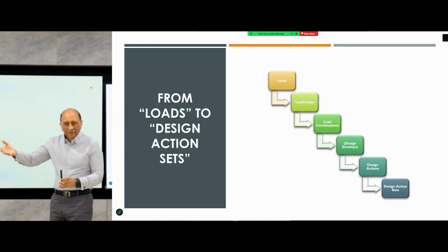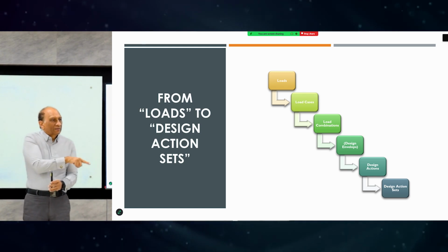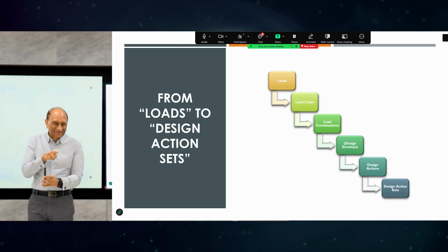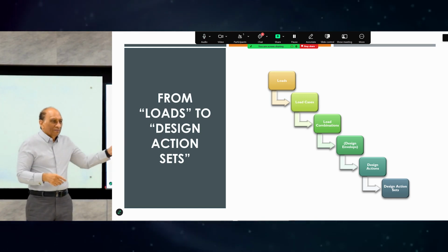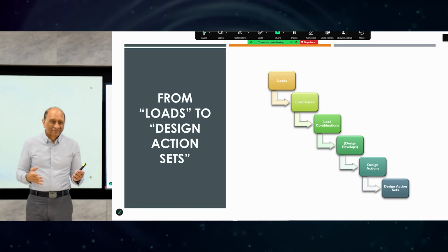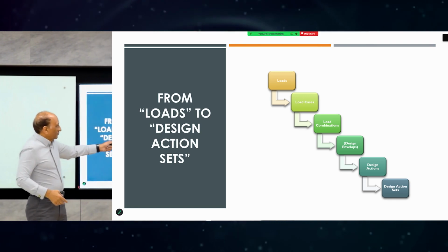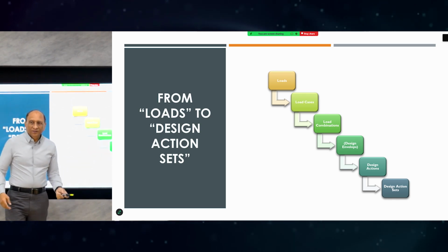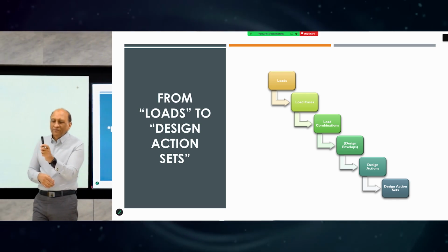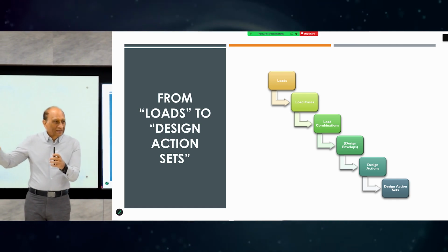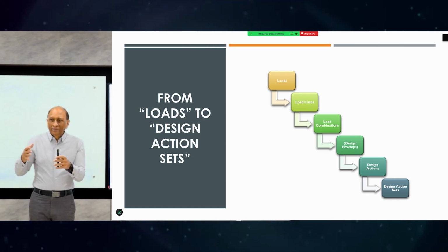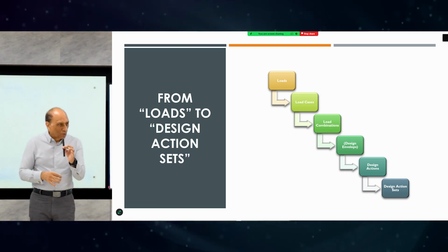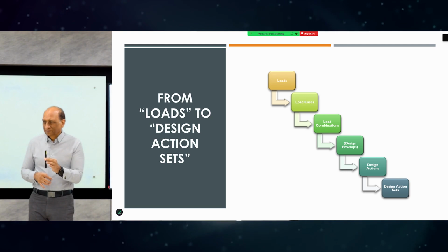So dead load, live load combined in different order, with wind load combined with different order. Remember, wind load combined with 20 different directions. So suddenly, lots of load combinations will be generated, because you have all the possible combinations to consider. And from there, you will get for this column, maybe for a tall building, without nonlinear, maybe 150 or 200 different bending moments for the same column.